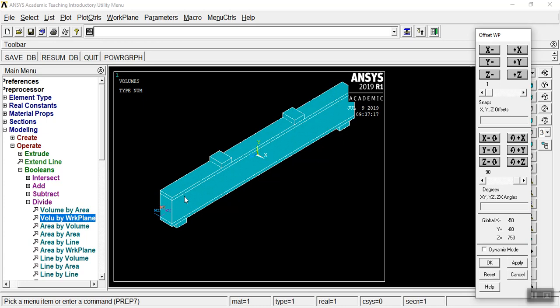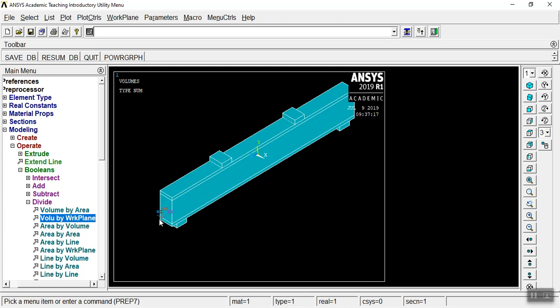So, for example, if I need a cover to be 20 millimeter in this way, then I need to move the local axis to 0 x, 0 y and minus 20, because we work now on the local, not on the global, so that wasn't the right way.